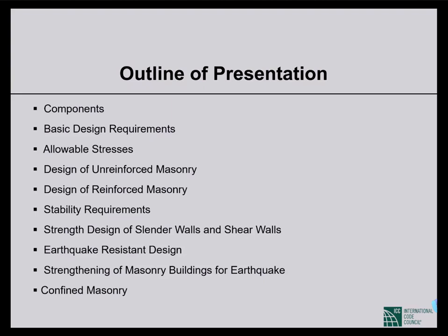So can you tell when we can consider a brick wall as a strut in the FEA modeling? What are the criteria? For infill walls, we model the infill walls as a strut. There are guidelines in different ACI publications, different FEMA publications. So for infill walls in a moment frame system, the infill walls are modeled as struts, but not the load-bearing walls.